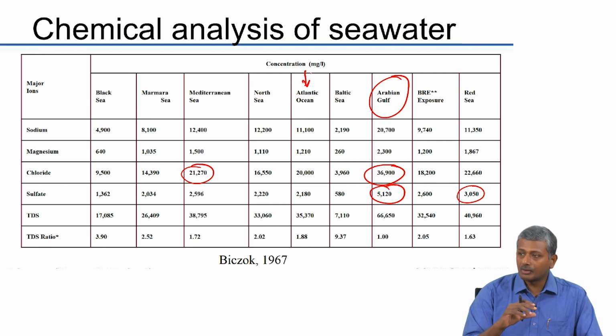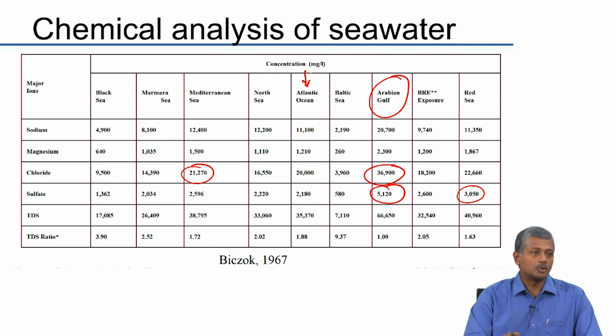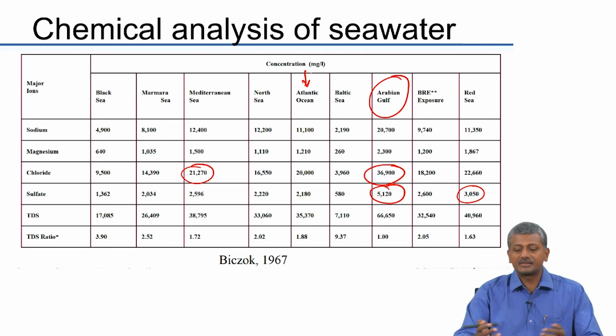And the performance of concrete can be critically affected by freezing more than the chemical attack happening because of seawater. So, you need to consider all these aspects happening together at once and be able to address these through appropriately designed durability investigations. Okay. So, just for your information, this is the kind of seawater concentration that you find in different parts of the world.